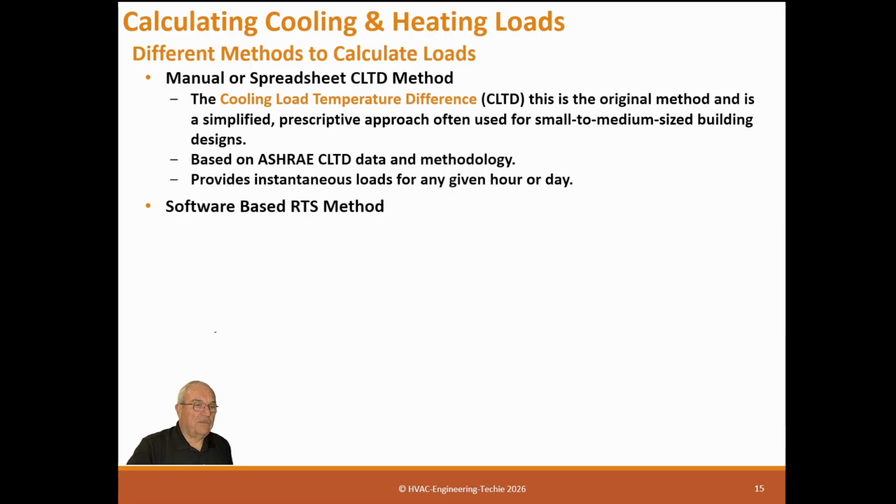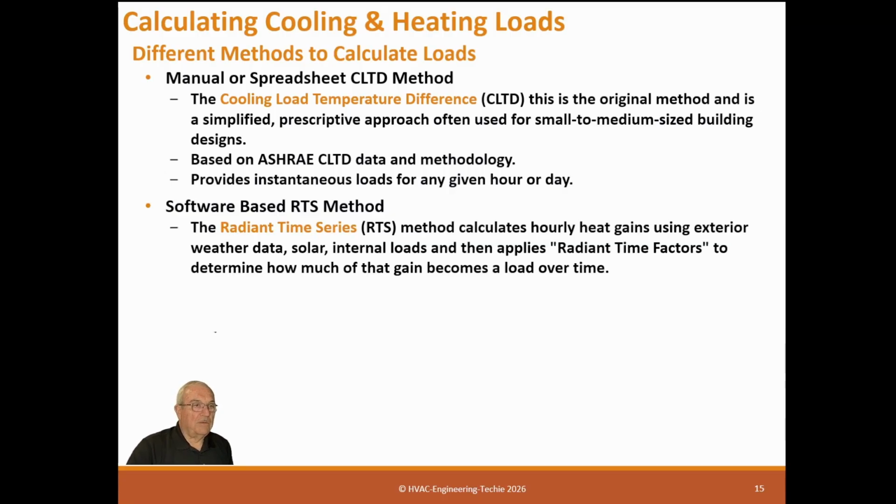The software-based RTS method is the next system they came up with, which is the radiant time series, RTS, and its method calculates hourly heat gains using exterior weather data, solar, and internal loads, and then applies radiant time factors to determine how much of the heat gain becomes a load over time. Now, this is the method that was developed by ASHRAE, well, at least by ASHRAE when I became familiar with it, and it is what the original heat gain programs were based upon.